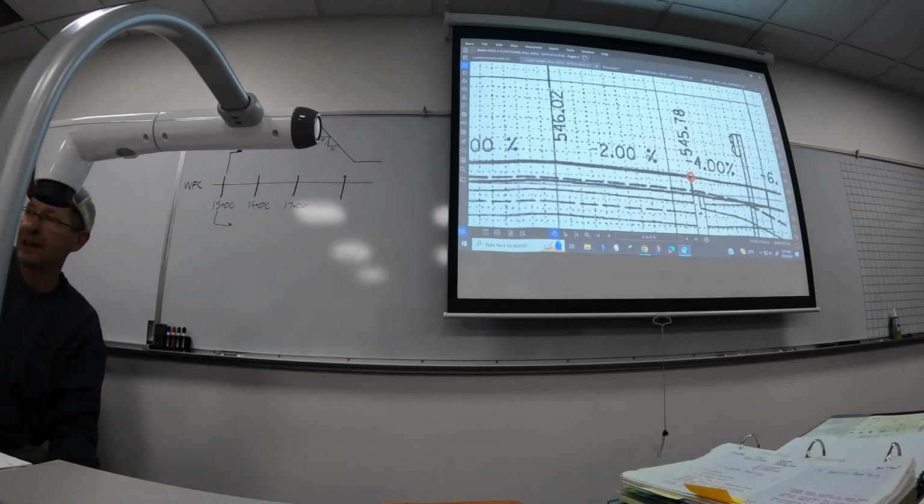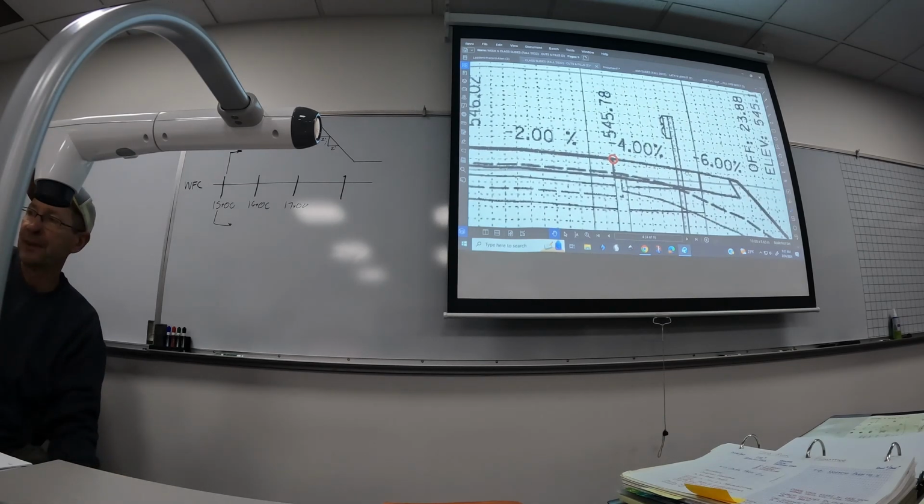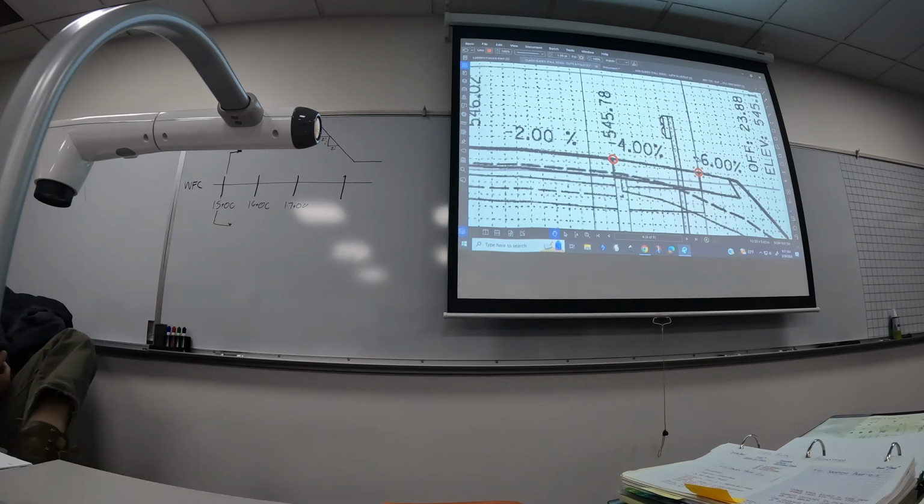So what would happen then if somebody said, hey, this shoulder out here, what grade is this? How could I find that? And if I knew that this is 8 feet, let's just say, because I'm counting 1, 2, 3, 4, 5, 6, 7, it's 8 feet. So the shoulder is 8 feet wide, and it's at 4% slope. What do we do first?